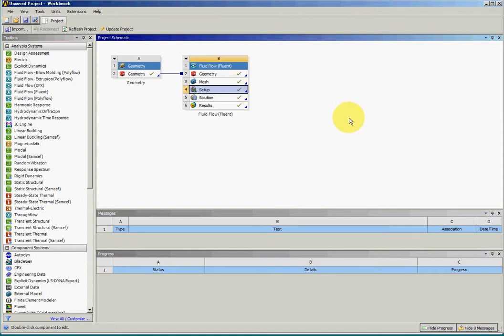The first step will be the geometry and meshing. The second step will be the initial conditions, defining that there's water in the channel, and the channel will be running water. And the third step will be the boundary conditions. We define the inlet mass flow rate of 0.5 kilogram and outlet surface, the pressure outlet of 1 atmosphere pressure.